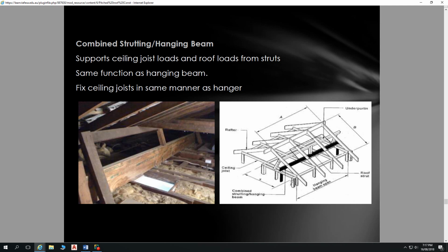Also, such big pieces of timber like this one down in the bottom left-hand corner here are getting very expensive to buy, because there's only so many very big pieces of timber you can get out of a tree. When you cut a circle into lots of square shapes, you're very limited to the number of square shapes you can get out, and you get smaller and smaller pieces. So you get many more small pieces out of a log than you do big ones. So those pieces of timber are far more expensive, but pieces of timber for making veneers are cheap.